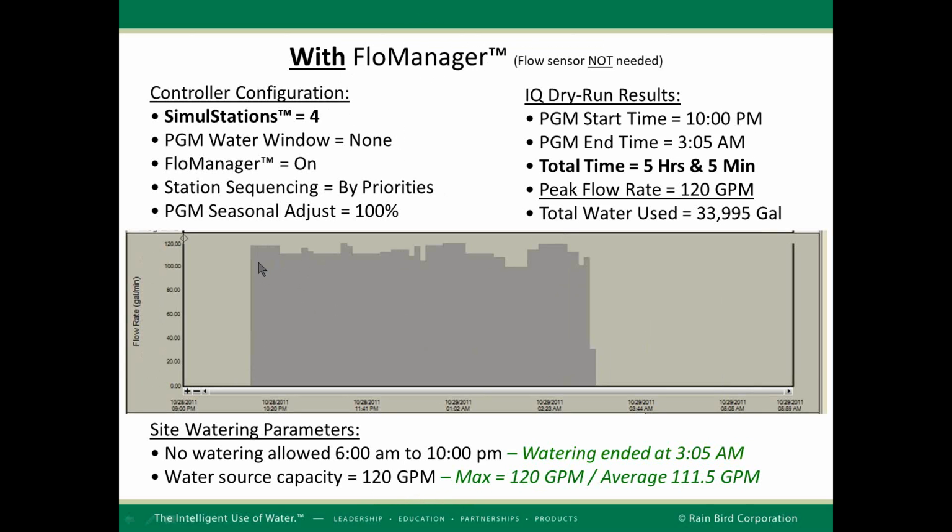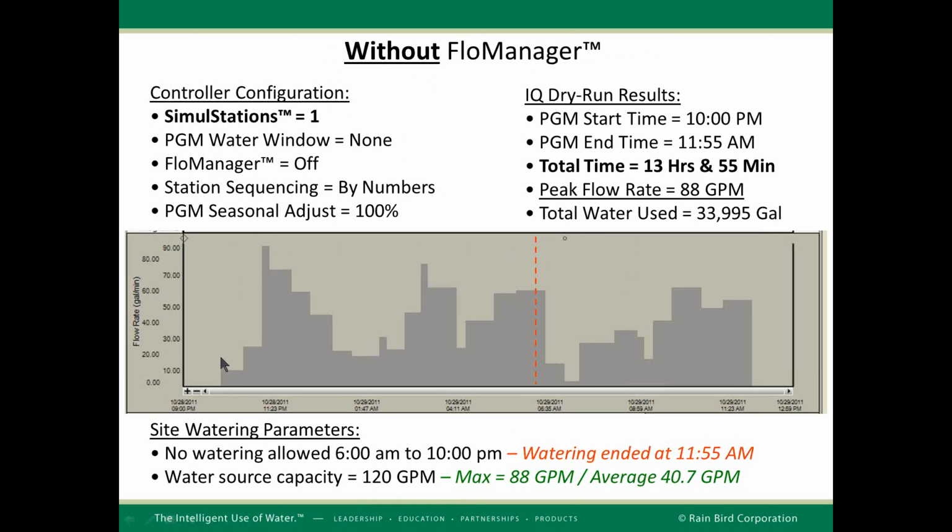As you can see, a pump station and a VFD would much rather operate within the efficiency of where that pump is supposed to run, as opposed to having a pump station turn on and off, on and off, finally turn on for only a few minutes, get back down here, it's turning on and off, on and off. You're cycling that pump and you're just tearing those drives up. You're not doing yourself any favors with the pump motors or the life expectancy of that, and your energy consumption is much, much more because you're running so much longer.